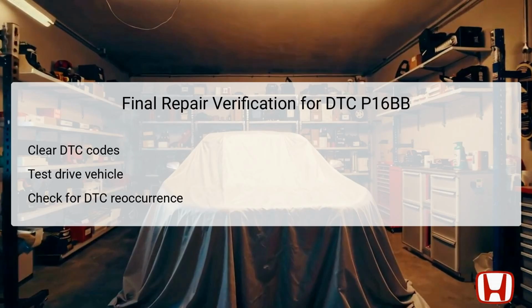After all necessary repairs and inspections have been carried out to resolve DTC P16BB-00, it's essential to conduct a final verification process. Begin by clearing any stored DTC codes from the vehicle's PCM using a diagnostic tool. Following this, a test drive is crucial to observe how the vehicle performs under normal operating conditions.